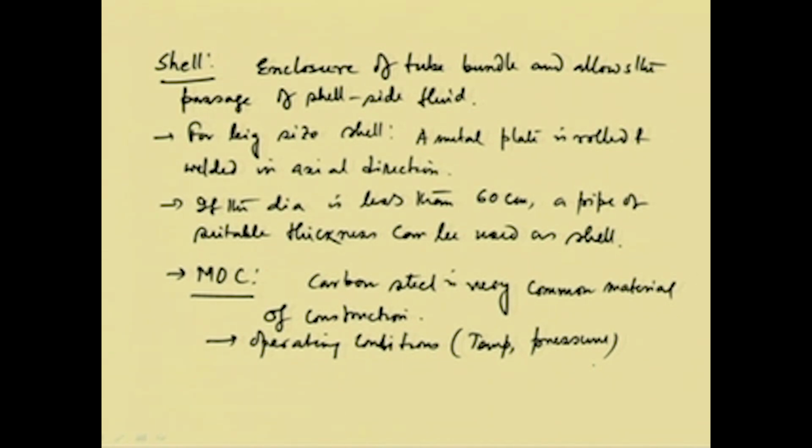Particularly the temperature is very important, because the fluid reactivity or the corrosion behavior of a fluid on a metal surface depends on the temperature. The most important thing is that the fluid used for heat exchange, which is passing through the shell side, should not corrode the shell side surface.